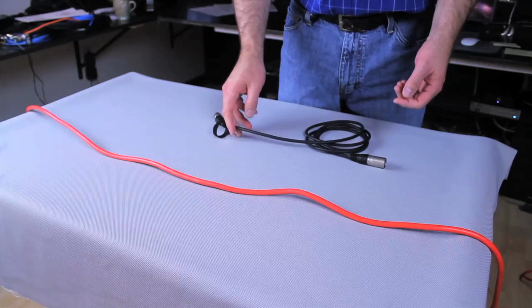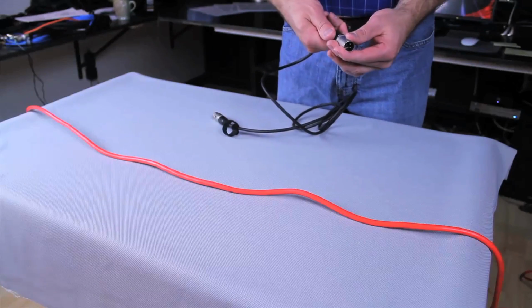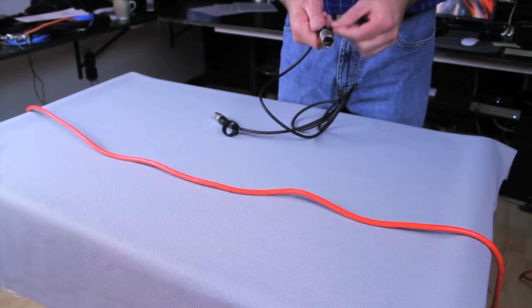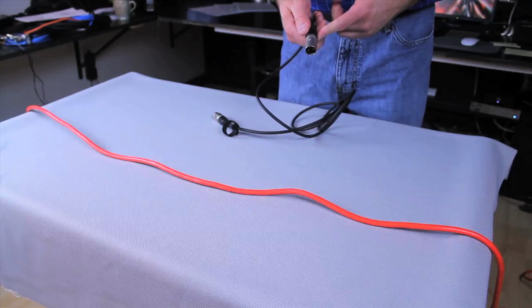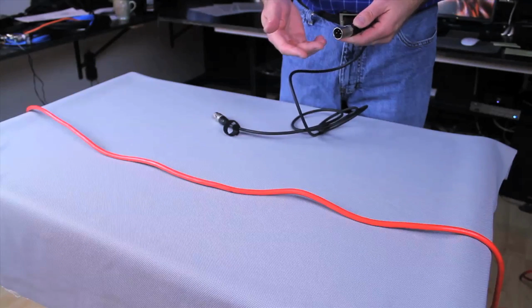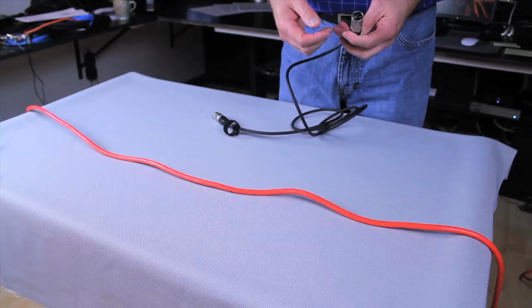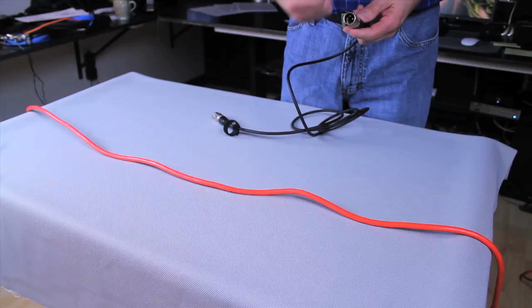The other thing is to take one of your audio cables that are coming in, you simply open it up and you cut that shield. Remember the braided wire that we had? I have one of those cables in my toolkit that I take along in every location, and I have it clearly marked that it has no ground.